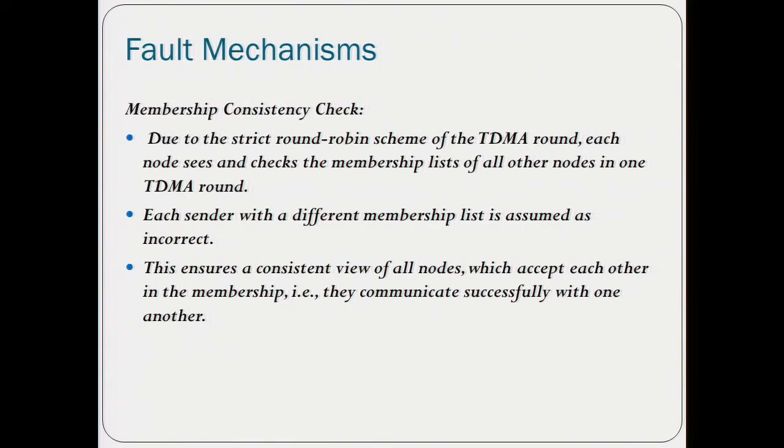If you notice that the guy keeps on writing, even when it is not his time. His assigned slot is stepped over, which means something wrong has happened, because you determine the slot and you tell the node that he has to communicate everything he needs to communicate in that slot. So if it oversteps the boundary, it means something went wrong.